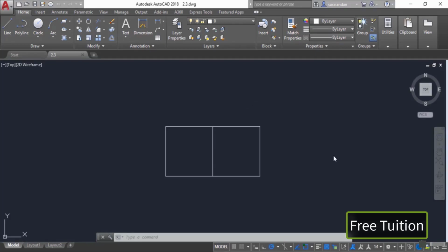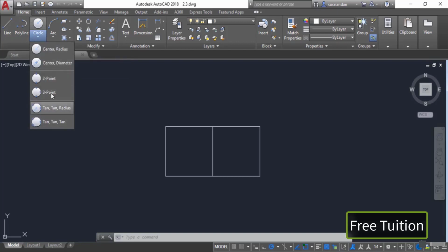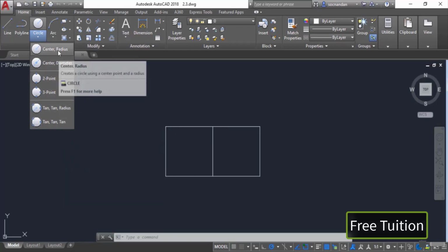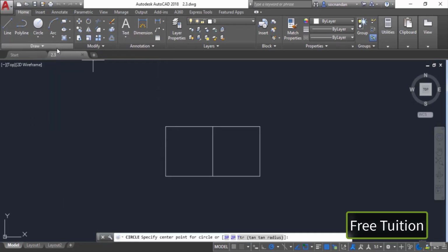In this video, I'll tell you about the circle command of AutoCAD. So you'll find the circle tool here on the draw panel of Home tab, and when you click on this small arrow, you'll see the circle flyout with 6 different methods of making the circle. So the most basic method of making a circle is the center radius. Now in order to select the command, you can click on this center radius option, or you can also use its command equivalent, circle or C.